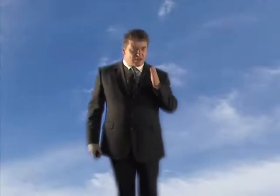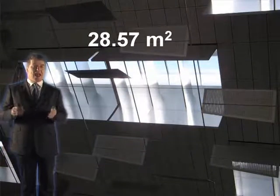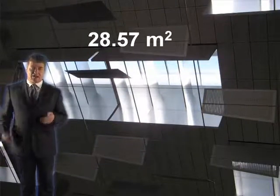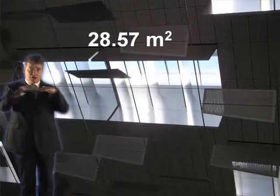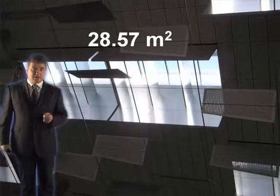This tells you that you need at least 28.57 square metres of inlet air to replace the air that's been extracted. So you've got to provide that and make sure it's below the smoke layer. So there's got to be at least that area to get those people out of there.